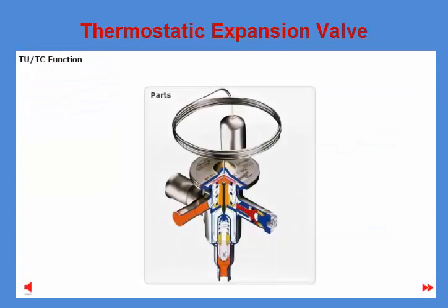The TU-TC thermostatic expansion valve is designed as a completely hermetic valve with easy to solder bimetal connectors. Only solder connectors are available. The entire valve is in stainless steel. The valve was introduced to the market in 1995 and is particularly used in ice cube machines and transport refrigeration. The standard version has a fixed orifice, but a version with exchangeable orifice is available.